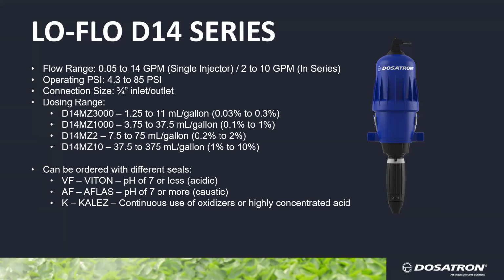Yeah, and I'll jump in, Justin. When it comes to seal types, this is one of those considerations that across the board we have. You'll notice that our standard is always Viton in hydroponics, horticulture, greenhouse, kind of any irrigation sector. Viton becomes your standard. So those of you that don't really worry too much about seal types when you're ordering, you're more than likely getting the right thing, right? Because so much of what we do in this world is acidic or neutral to acidic.